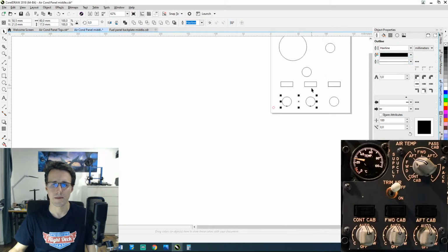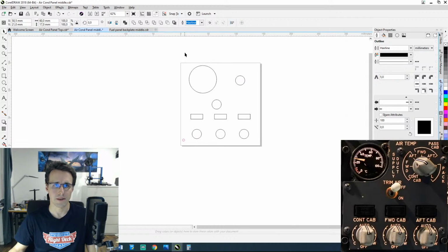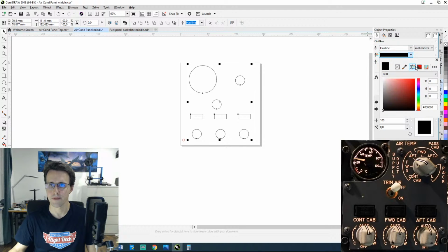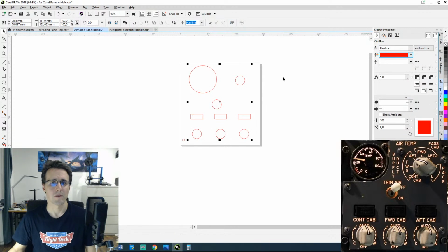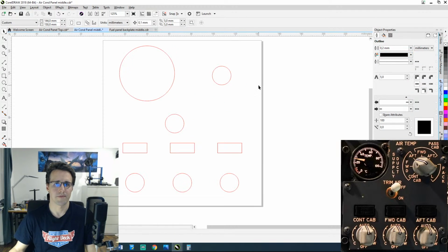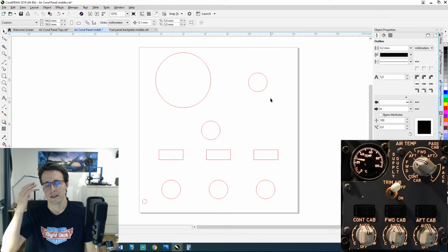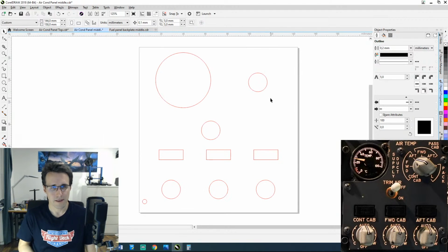There. Okay, because they are mixed up. Can I now do this? Yes. So why am I coloring them red? Because I will cut this out with a laser later, and red is automatically recognized as a cut, not as an engraving. That's all behind this.